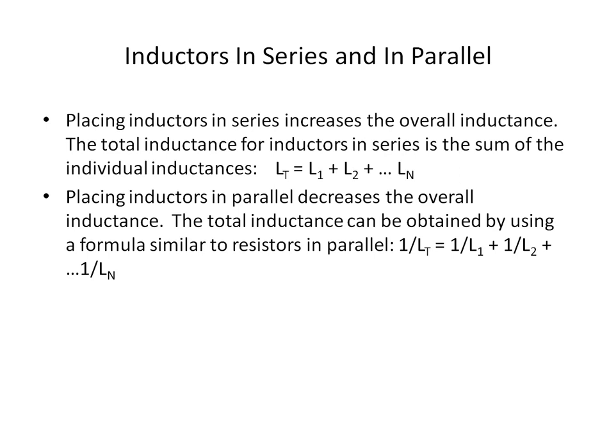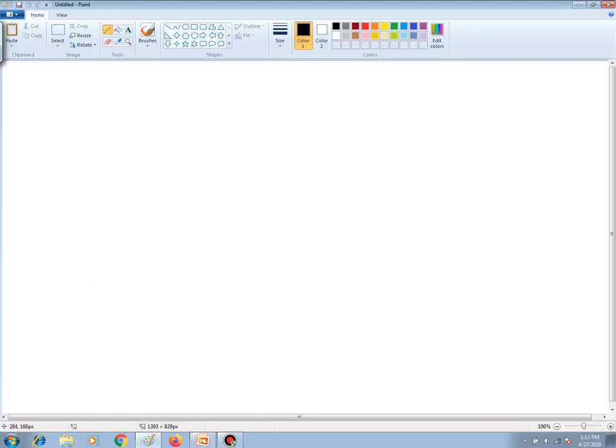Just to make that point perfectly clear, let me show you. Let's say we had some inductors in series, such as this. These are just air core inductors; I don't have any type of core being shown. From points A and B, let's say this was 0.5 henries, this was 1 henry, and this was 4 henries. The total inductance, L total, would be the sum of those, which is 5.5 henries.